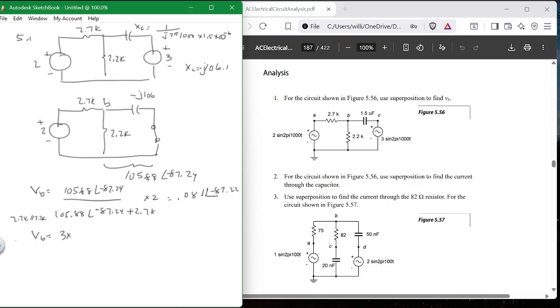That's an easy one. R1 R2 over R1 plus R2. I still like doing the 1 over 1 over rule, but you decide how you want to do this one. It's 1 divided by 2,700 plus 1 divided by 2,200. Boom.